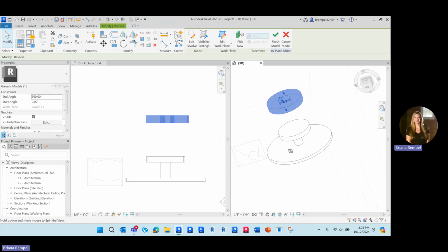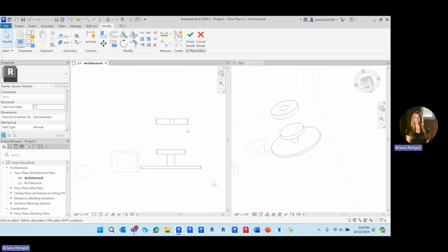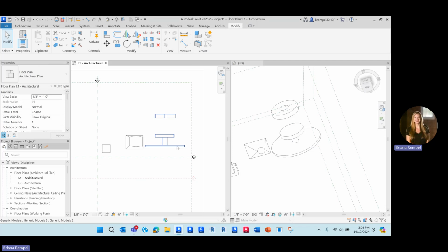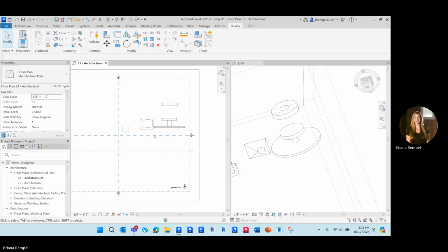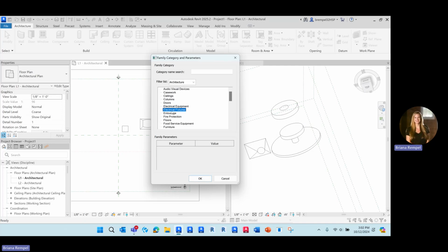All right, also great for, think of it too like a lampshade, base of a lamp, legs, table legs, chair legs, really useful tool here. So I'll go ahead and finish that for the revolve. I did draw two of them in that component. That's why they're both selecting here as I look at it. And I'm going to do another component in place.